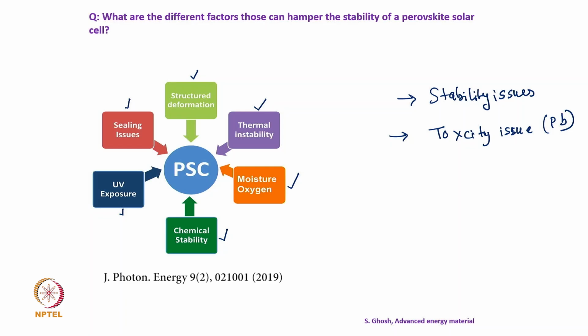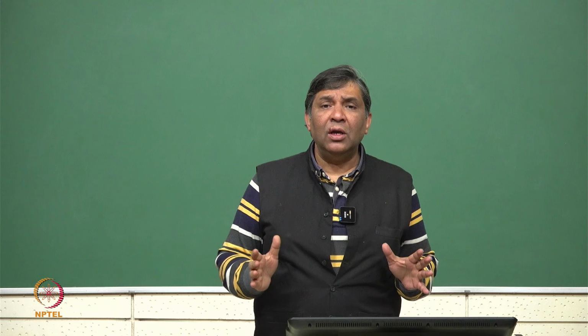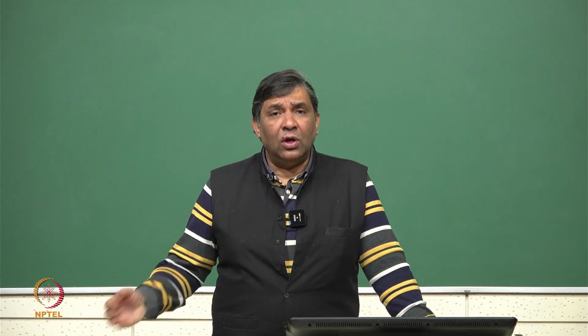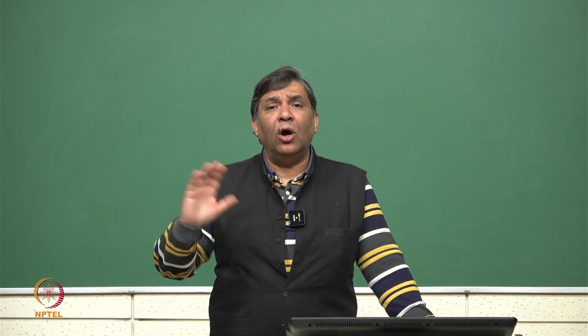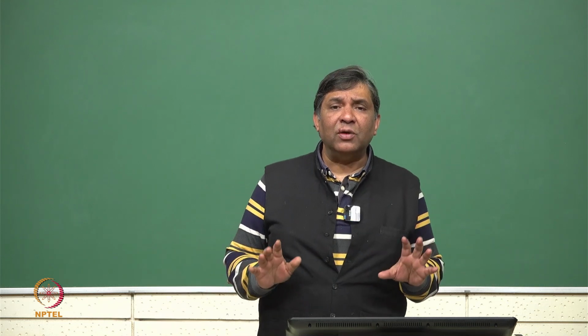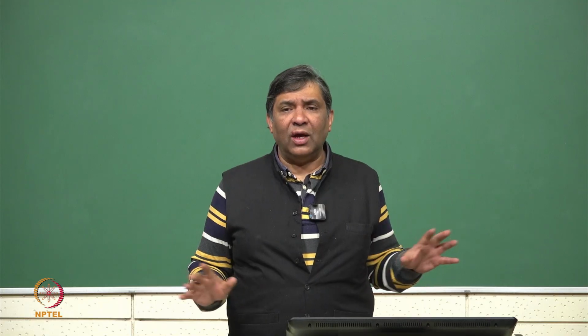Okay. So, what we have seen in perovskite solar cells, although it is highly promising with quite high efficiency, because of the stability issue and toxicity issue, the perovskite solar cell is still facing problems. Although a lot of research work is going on into how to make this perovskite solar cell stable, there is a structural factor, also known as the tolerance factor, which one can calculate to design the material, and try to optimize that tolerance factor in order to make a stable structure, and also one has to keep this perovskite material slightly sealed from the environment.